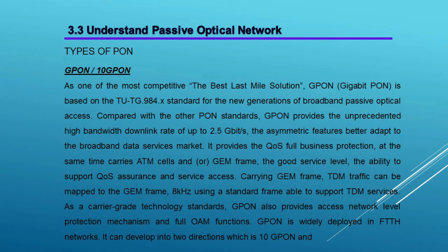Carrying GEM frames, TDM traffic can be mapped to the GEM frame at 8 kHz using a standard frame able to support TDM services. As a carrier-grade technology standard, GPON also provides access network-level protection mechanisms and full OAM functions. GPON is widely deployed in FTTH networks.